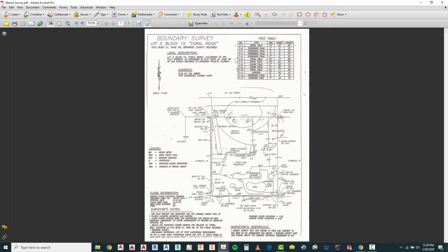I'm going to start by drawing our property lines to the actual dimension, but in order to locate these trees where I want them located, I'm going to have to bring in my survey as an X reference, PDF, and then take a measurement from that. That means that I'm going to be scaling my survey when I do insert it. So let's go back to our drawing.